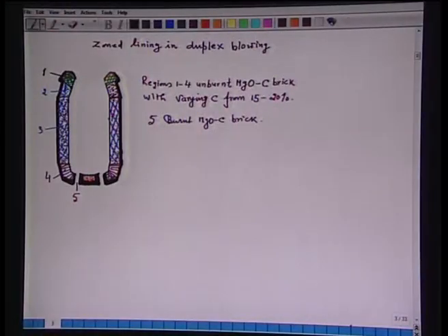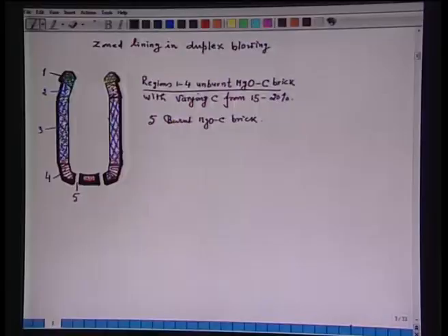There the corrosion and erosion of the refractory material of the bottom tuyeres determines the life of the bottom, because when the tuyeres are eroded you have to replace the tuyere and accordingly the life of the converter is affected by that. So, here also the different zones are lined with different refractory material.